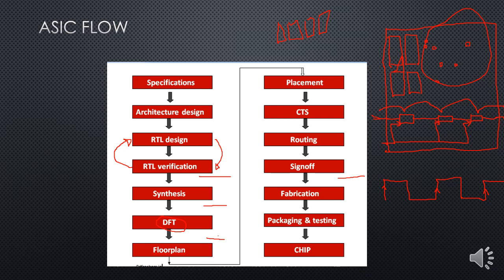Routing, in the sense that so far we are saying that communication is present from here to here, but it's only logical. In order to connect this output pin to this input pin, we need to have some physical connections, right? That is done with the help of metal shapes. With the metal shapes, we connect the output pin to the input pin. In most cases, these metals are nothing but copper. In some cases where resistivity matters, we also use gold, but most of the time we use copper.